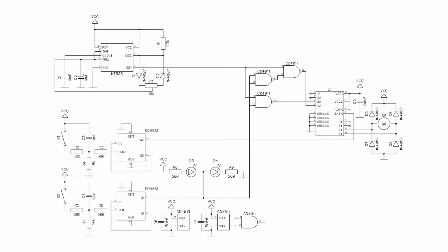We also decided to use buttons with 1 stable state. Simple systems based on D-type flip-flop will help us. The combination of the inverting Q-negated output with the D-data input will create a system that will change the output state Q to the opposite at the moment of voltage rise at the CLK input.